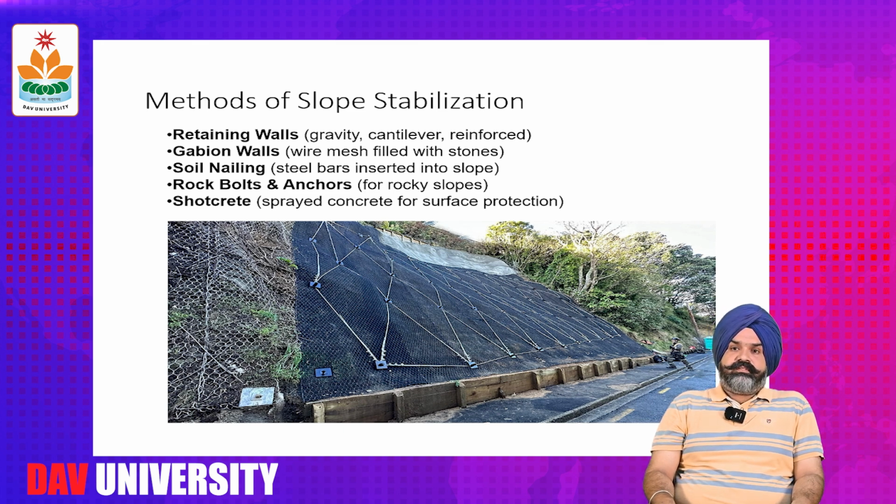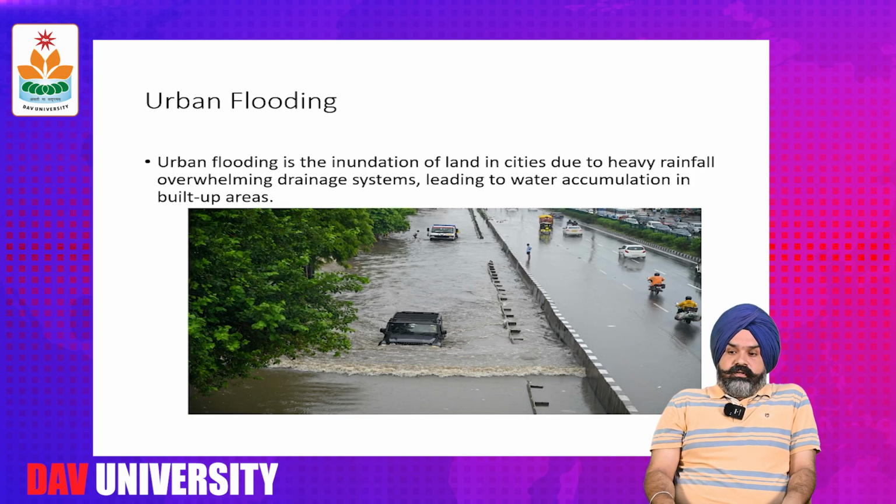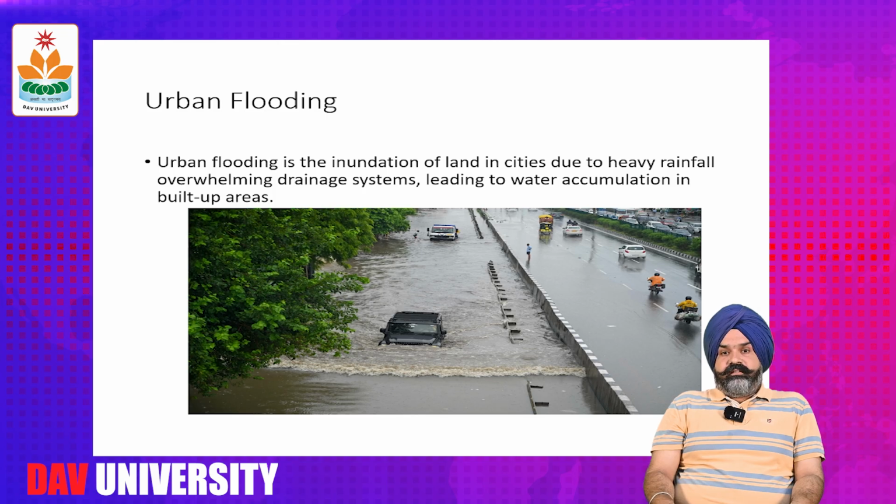As I have discussed, the most common techniques for stabilizing soil are rock bolts and anchors and shotcreting. Basically, shotcreting is most important. It is economic as well as most commonly used. Rock bolting and anchors are also commonly used, but they are quite expensive as compared to shotcreting.